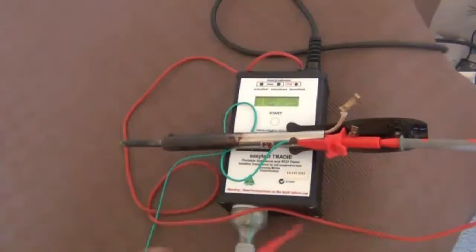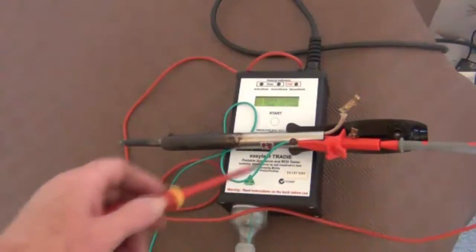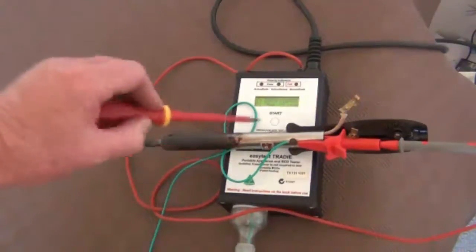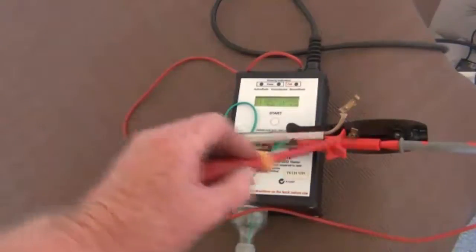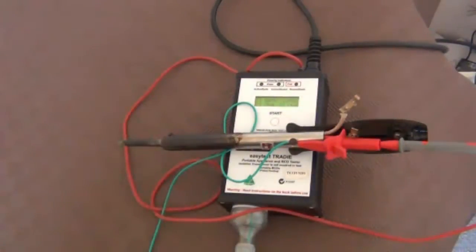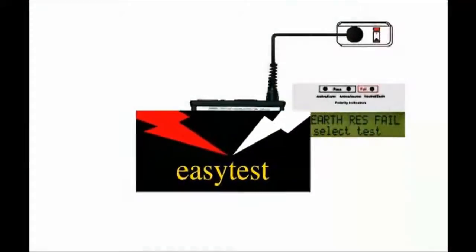It tests the resistance of the circuit from the earth, through the earth wire of the lead, to the earth connection, and back to the tradie unit. It has to be less than 1 ohm, and that is the earth resistance, or sometimes called the earth continuity test. We're going to test an earthed appliance.